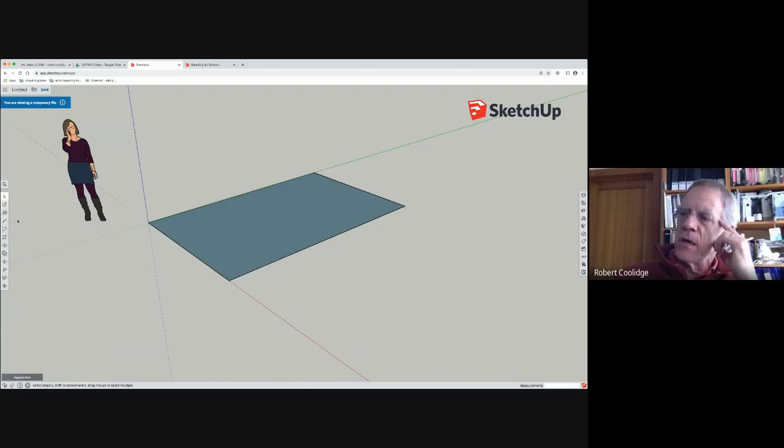It doesn't matter at first when you play with it, but when it comes to 3D printing, for example, you have to have all your faces right side out, or the STL file that goes to the printer won't understand it. Because this isn't a solid modeler, it's up to the user to be sure that you got clean solids when you do 3D printing.